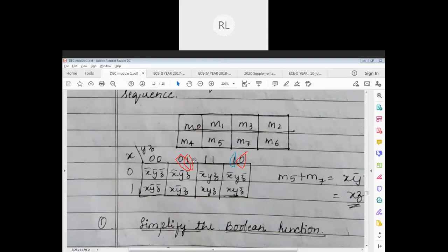Yes, sir. There is more than one bit change, right? But what is the rule? The rule is that I should just have one bit change. But here the first bit is also changing, 0 and 1 is also changing, right? You can see this is also changed, and this is also changed. We do not need many changes, we just need one bit change. So that is why instead of keeping it here next to it, I actually keep it here, so that I will have just one bit difference.